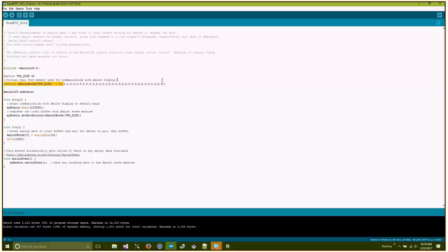I don't need one this long. I only need one of the variables for this specific example, but just to reuse this code over and over again, we just make it a wide one. We've chosen 32, that's arbitrary, as the size of this array. The actual array on the Amulet side is 256 variables. But when you're talking about all the bytes, words, 32-bit colors, and 26-byte strings, if we added all of those into this library for you, it would take up about 8K of RAM.